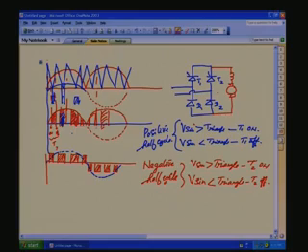How we can have output voltage control with unity power factor, for positive output voltage directions using PWM, we will be studying in the next class. Presently available IGBTs make it convenient to have variable voltage control with unity power factor, using high frequency PWM, that is, a front end AC to DC PWM converter with unity power factor. So, a lot of converters are available; one converter we will study. Originally I think this converter was used for traction drive applications as a front end AC to DC converter, where the input was single phase. Then how the harmonic suppression can be done with the sine triangle comparison, we will study in the next class.